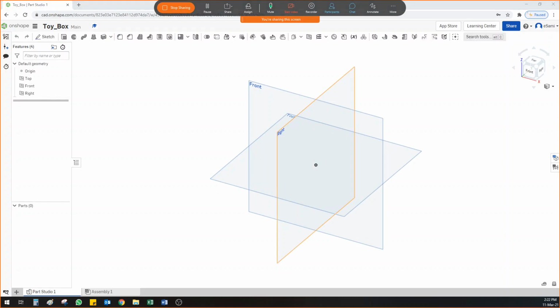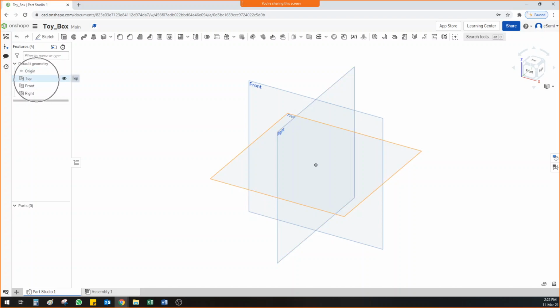Once the options are loaded, you will go to the program itself, and if you can notice guys, it is the same as SolidWorks. You can see here it has the front plane, it has the top plane, it has the right plane. And on my left side, I have all the features design tree similar to SolidWorks. And what are the feature names here on the top? It is extrude, revolve, same as SolidWorks. Sweep, loft, I have thicken, I have fillet, chamfer. And guys, it's the same set of features. Usually, sometimes there are more, sometimes there are less, but you can find your way around.